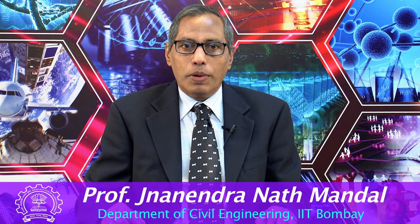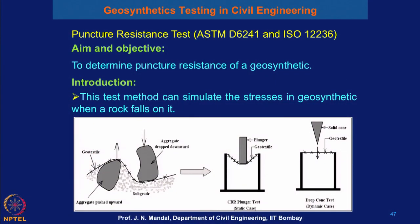Now, we will perform the puncture resistance test, as per the specification ASTM D6241 and ISO 12236. The main objective of the test is to determine the puncture resistance of a geosynthetic material. This test method can simulate the stresses in the geosynthetics when a rock falls on it.